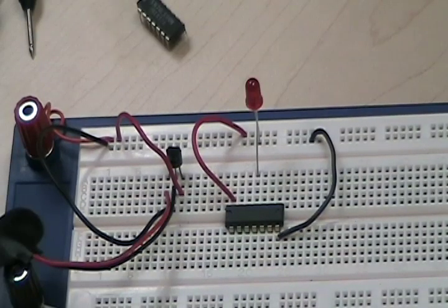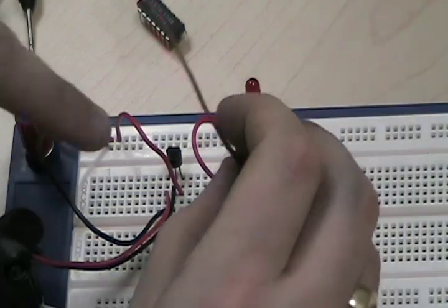All right, guys. So this is an OR gate. Ow! The exact same pinout as the AND gate we just used. This is a 74LS32, but we're using OR gates. So I haven't powered it up yet. What I'm going to do is ground both the input signals.